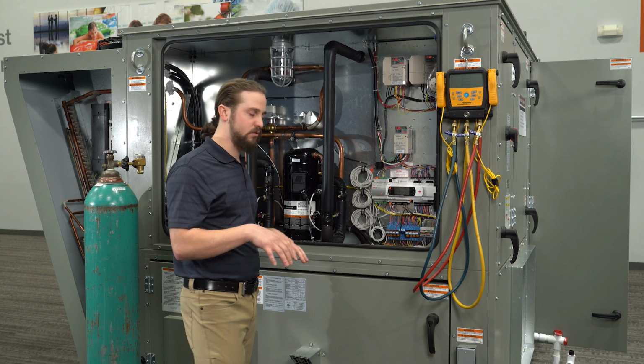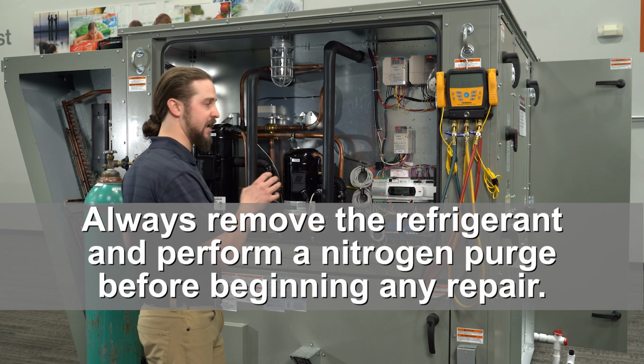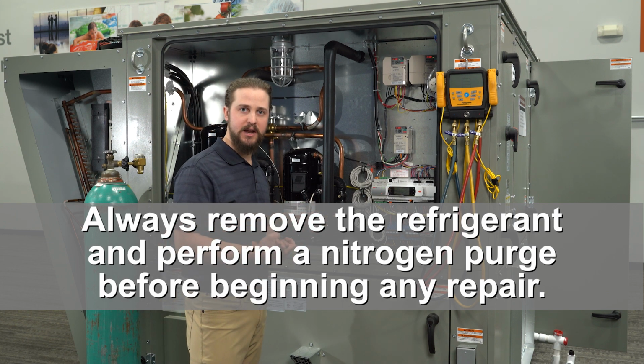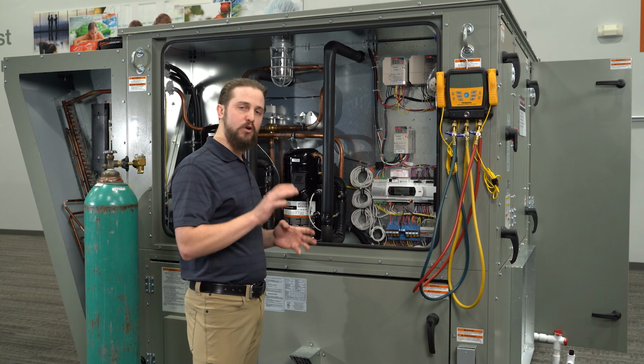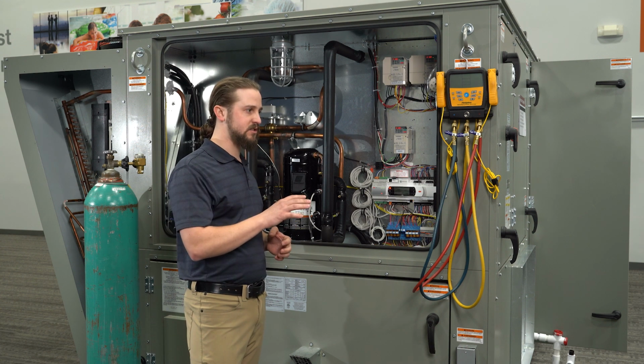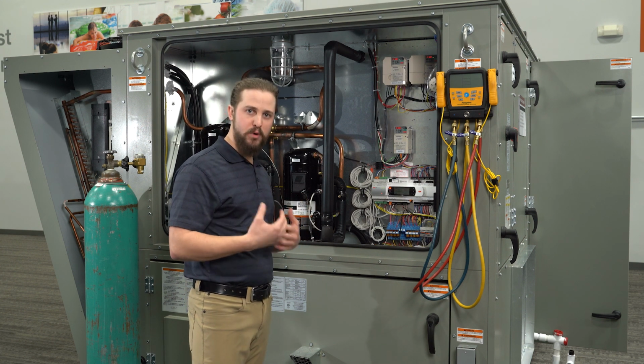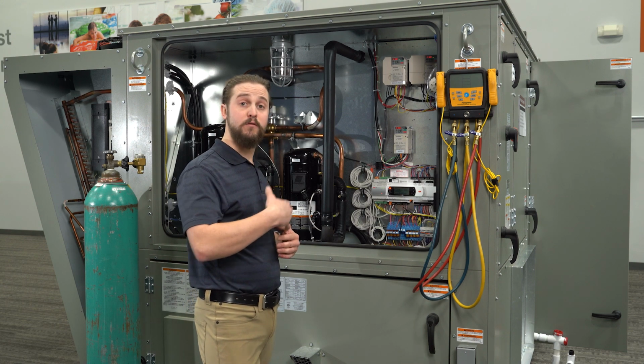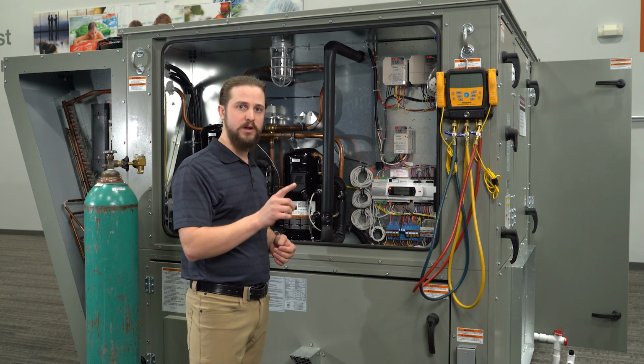For the sake of this, we are going to be adding nitrogen. I already removed the refrigerant just for the sake of this training exercise. Before we do that though, I do want to discuss why I removed both circuits of refrigerant in order to fix a leak on just one circuit.